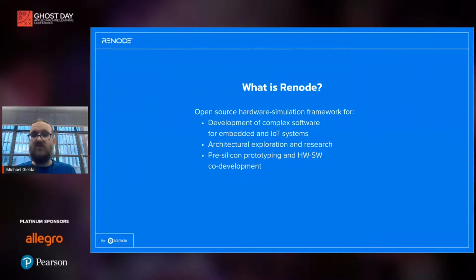So Renode is a simulation framework, as I've mentioned already. You can use it to develop complex software for IoT systems, but also you can do exploration and research on it. The interesting thing about it is that it gets very easy with Renode to create some virtual hardware. And of course, we typically target existing platforms because having something that you can physically test as well is a good idea. But there is nothing stopping you from building a system that wouldn't normally exist and testing stuff in a system like this and then deciding, okay, I am going to build that system now.